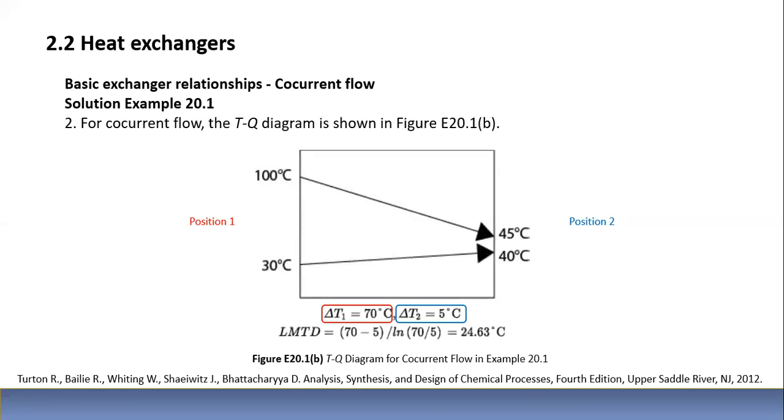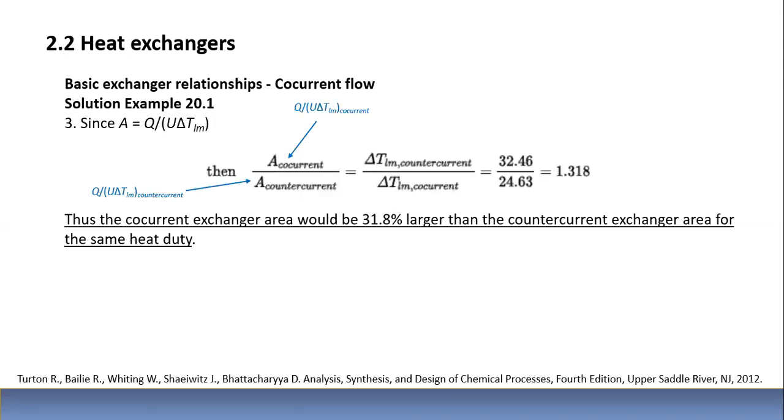So it's not exactly the most efficient procedure that we can use or operate in an industrial plant. If we're going to use concurrent configuration, that will not be the most efficient way to exchange heat. The most efficient way would be countercurrent protocol or countercurrent operation.